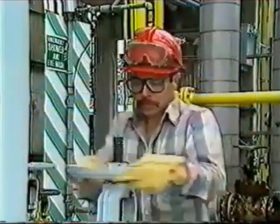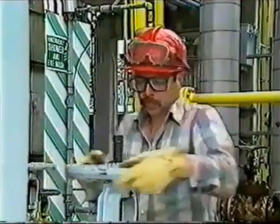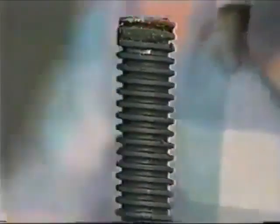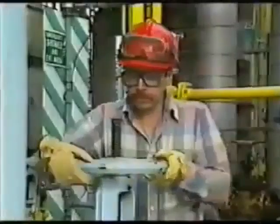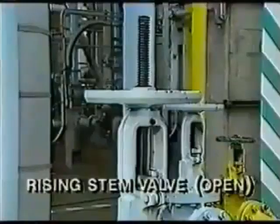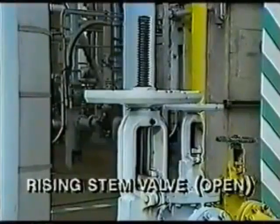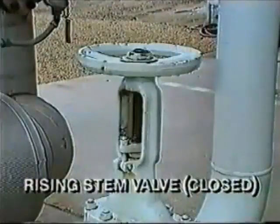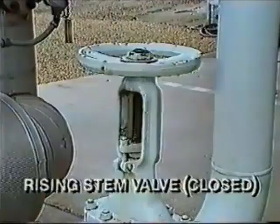As the hand wheel is turned counterclockwise by pushing with the right hand and pulling with the left hand, the stem and attached gate rise and the valve opens. Turning the hand wheel in the opposite direction, or clockwise, closes the valve by lowering the stem and gate. Because of its design, this is called a rising stem valve. You can always tell if the gate is open or closed by looking at the position of the stem.